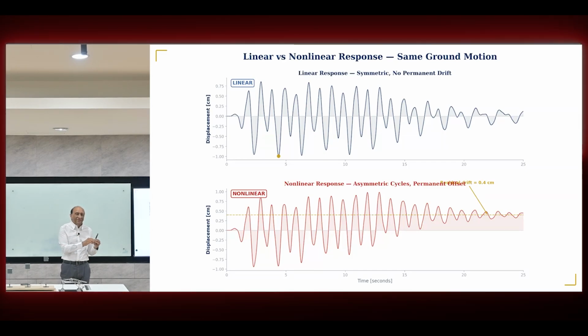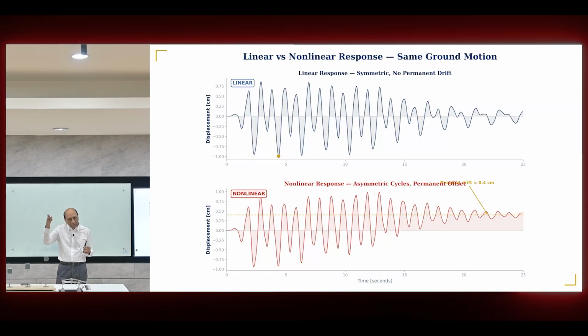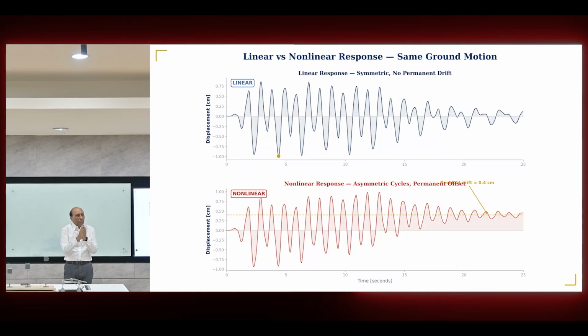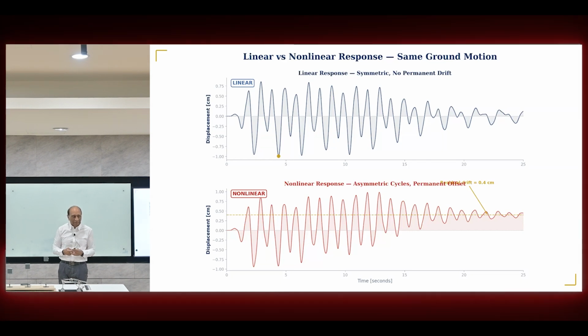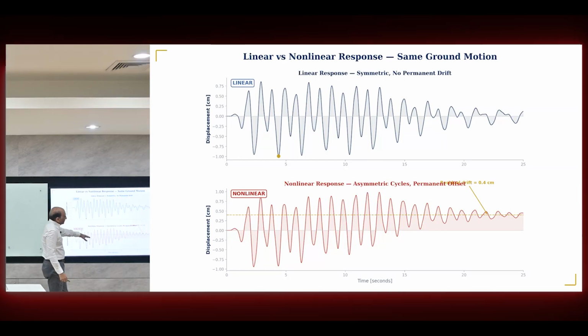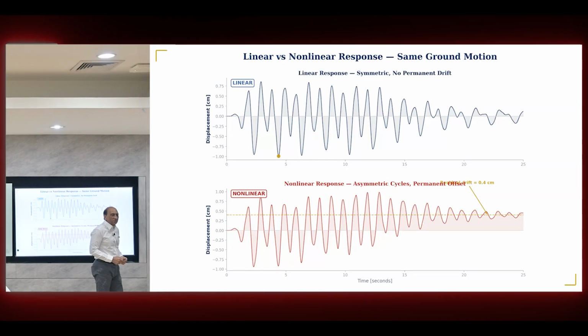This is a nonlinear inelastic response. If you remember the first course, nonlinear and inelastic, it goes a nonlinear way, doesn't come back to the same point. So that means the building is no longer where it started from. It will not return. It will be permanently deformed, which is the residual drift, or many other ways that you can measure it. So that's the key difference between the first and second response. Not only will this pattern be different, but it will not come back to zero.